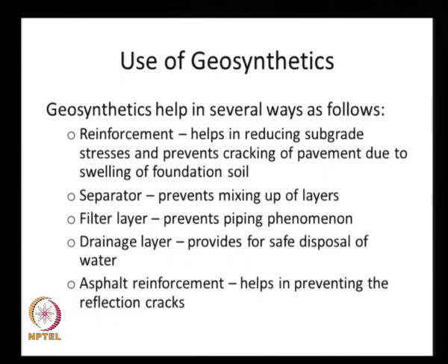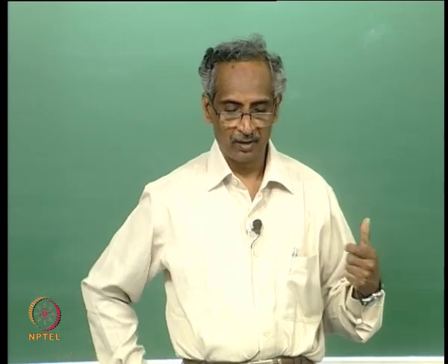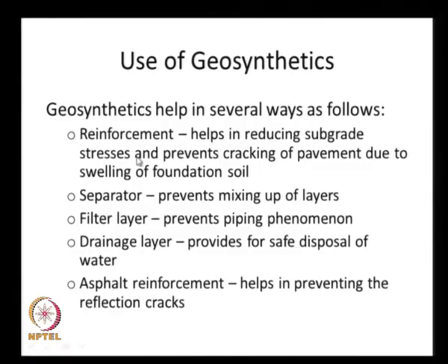So, now let us see how we can employ the geosynthetics for improving the longevity of the pavements and reducing the thickness, and also making them durable for a longer time. So, these geosynthetics help us in several ways in the form of reinforcement. When we use a geosynthetic as a reinforcement layer, it helps in reducing the subgrade stresses and prevents the cracking of pavement due to the swelling of foundation soil.